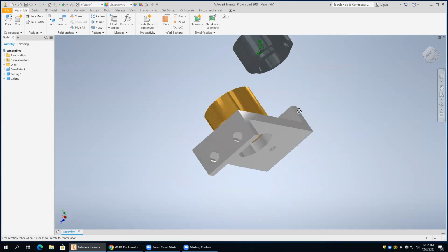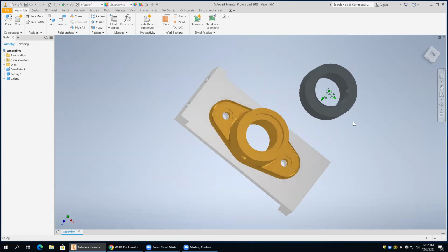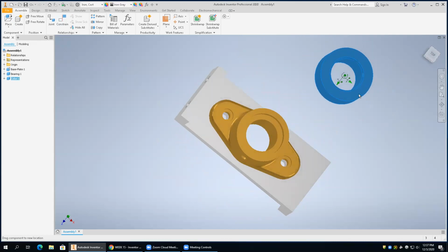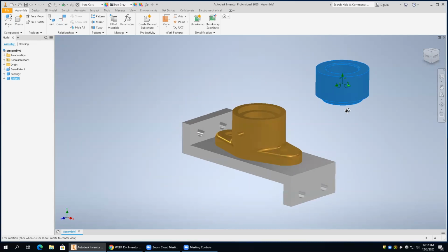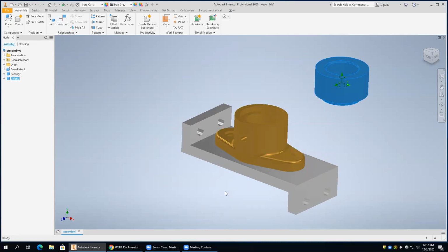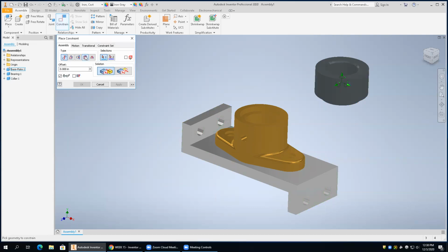And this guy has got multiple degrees of freedom. He's got 6. He can rotate about X, Y, and Z, and he can move in an X, Y, and a Z direction. Okay. Is that good for everybody? So when you have cylinders that line up, things like screws into holes and those kind of things, one of the best ways to do it is what they call, not the tangent one, I'm sorry. It's this one. It's called an insert.